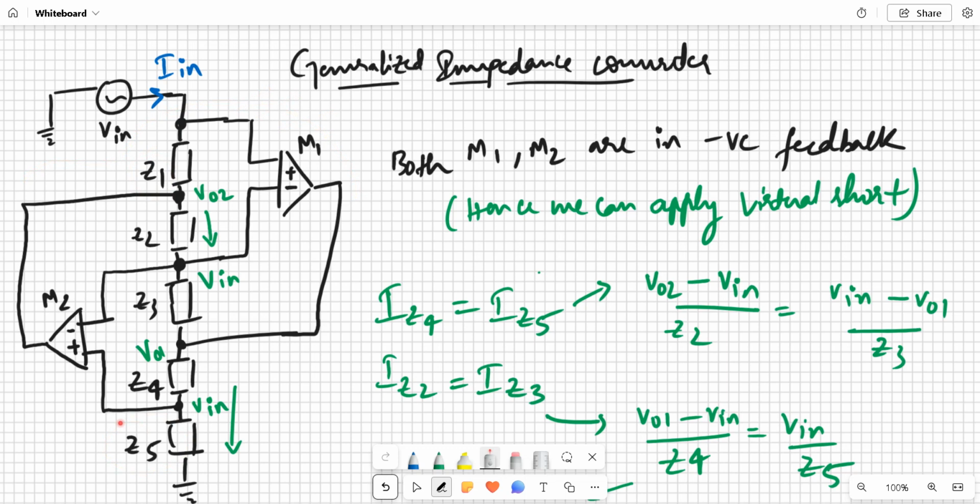This circuit has active components like an op amp, so this is an active impedance. You might have also seen an active rectifier. A basic rectifier contains a diode, which is a passive component. An active rectifier consists of what is called an active diode, which is a combination of a diode and a MOSFET or an op amp to enhance its working. Similarly, these impedance converters behave like an active impedance.